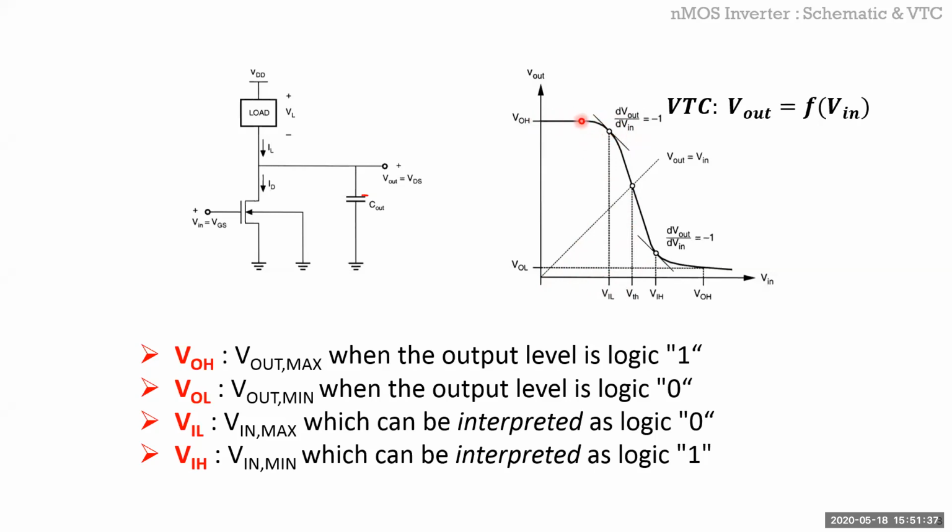So it is 0 here and slowly starts increasing negatively. And when it reaches -1, that's the point you want to stop and say, this is my input logic low. After that, I don't know what it is, but below that, from VIL to 0, I'll consider it as a 0. Why do we choose this number? Again, I'll talk more in detail about that.